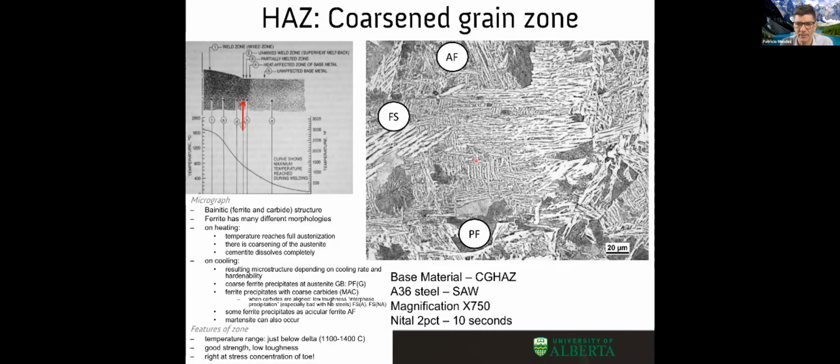let's go to the phase diagram here. Fine grain heat zone is around here. Coarse grain heat zone is here. Both are fully austenite, but now we have all these high temperatures that make diffusion very likely. We're not making a transformation by diffusing, but the grains are coarsening.